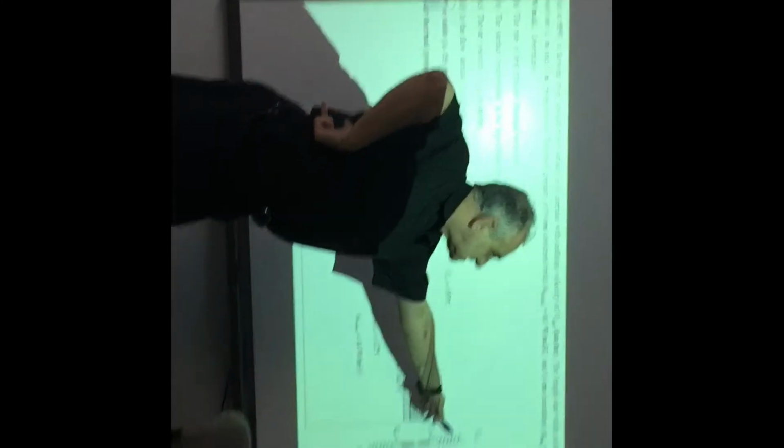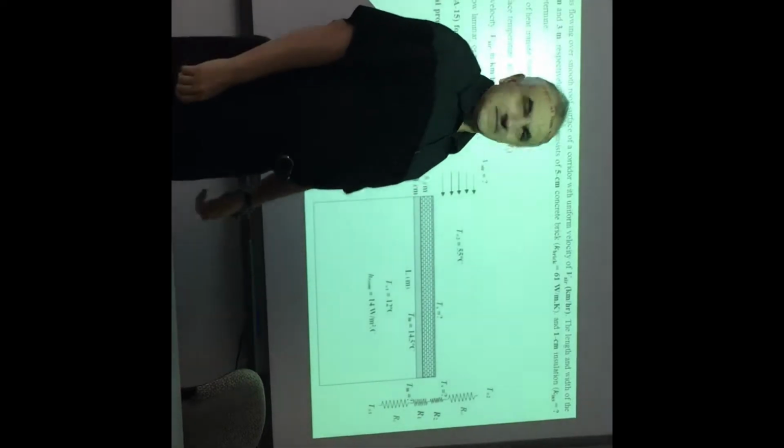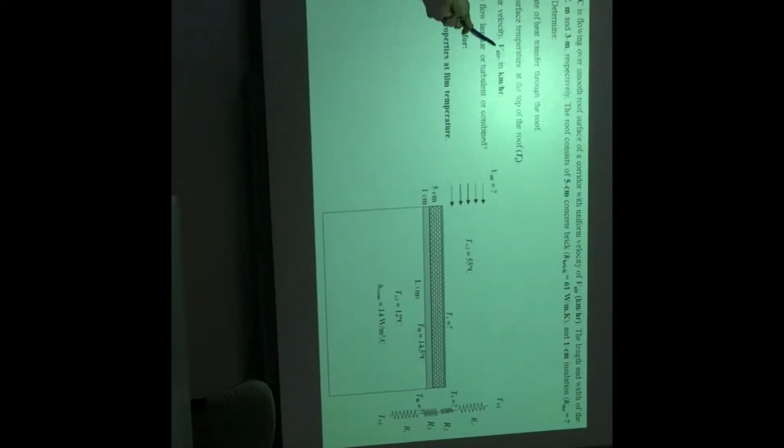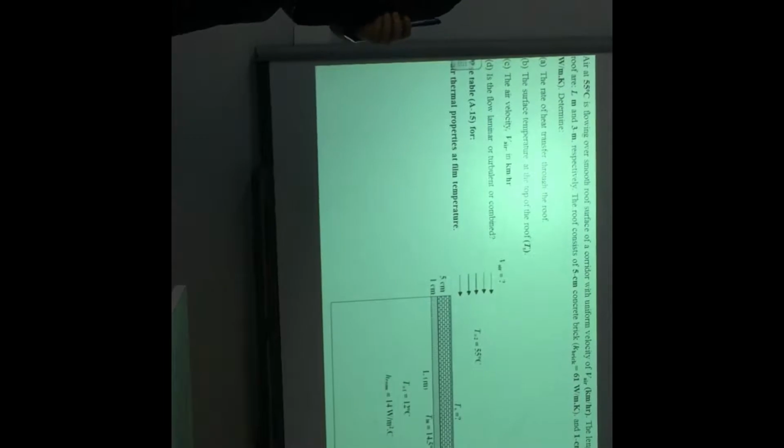So this outside resistance, we have h at the outside, which we don't have. The second one is also easier. Go to the third one, the air velocity. You need the air velocity. Now this is the hard part. To find the air velocity, opposite to what we discussed, we use the same concept but in the opposite way.